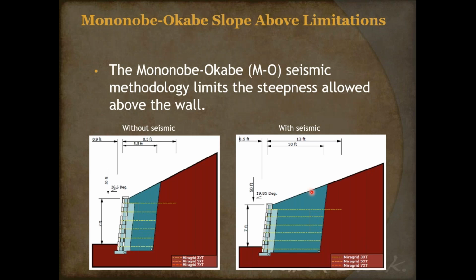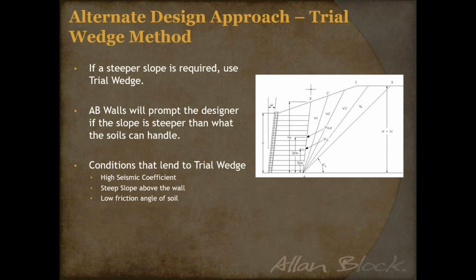It's probably the most widely used, but there are some limitations. Now, with computers, the analysis for the trial wedge method is now possible. It can be done faster, and it models site conditions a little bit easier. There isn't that same limitation because I'm not doing the numerator and denominator. It's all basically trial wedges. I take that wedge of soil and determine what that is, so I'm doing hundreds and thousands of iterations for this trial wedge. So I can do those steep slopes.